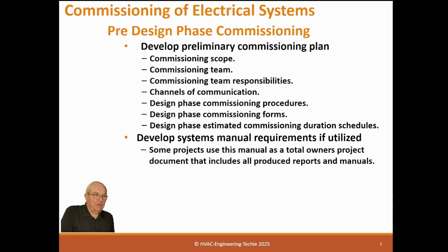I mean, a manufacturer will do an O&M manual for 10 different pieces of equipment in the series, and never tell you in the O&M manual which one's on this job. So it's better that the commissioner provides a system manual. They're big, and we do them in media. We don't do them in paper because they'd be a foot thick. We don't want them to be so large you can't deal with them. But they're really helpful, really good.